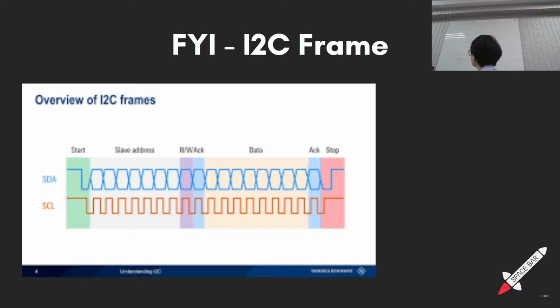So then you form a voltage divider between 3.3 volts, the 10K resistor, the MOSFET resistance, and ground. Because the MOSFET resistance is so tiny, it's basically zero. The line is basically 3.3 volts. Is that correct? Well, the line is basically 0 volts. Yeah, basically zero, my bad. But then, wouldn't that ground everything after it also? Yeah, everything will be ground. This whole bus will be ground.